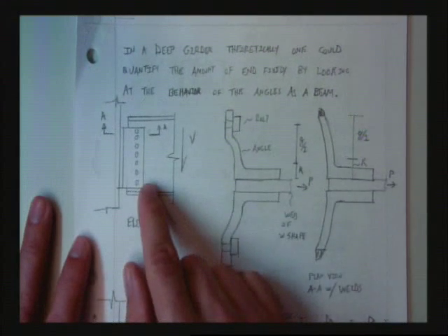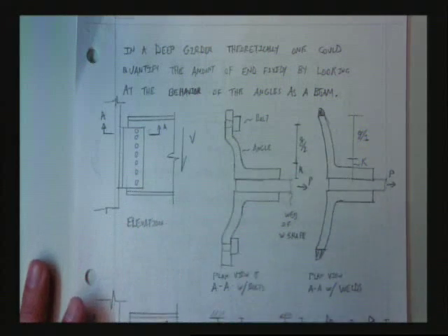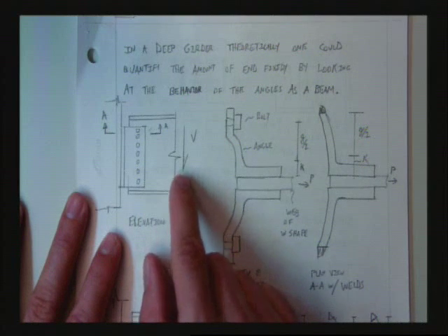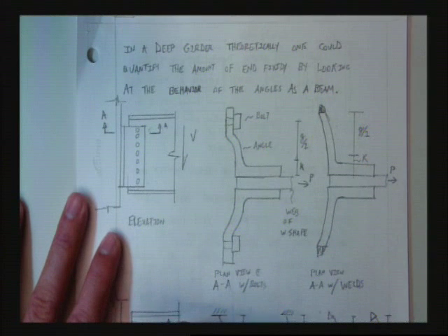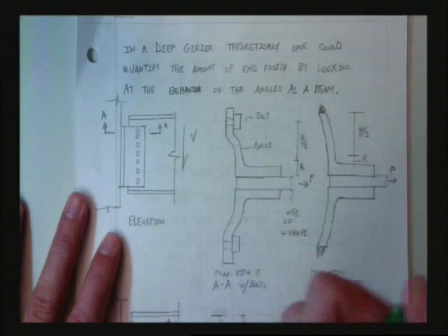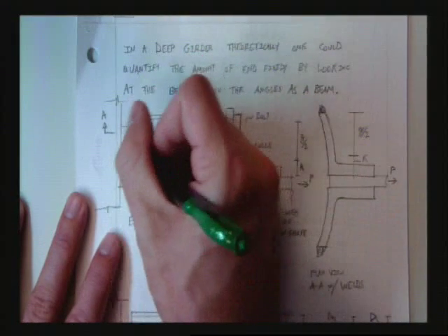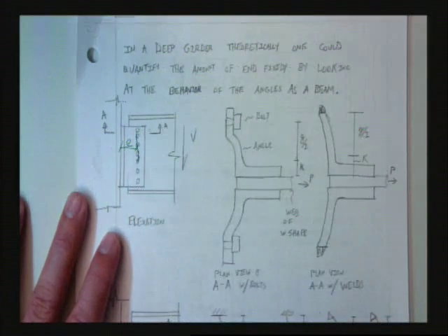So now what we have to think about is, okay, my gut tells me it's simple. I'm still thinking it's probably simple, but now since we have a shear on it, I'm going to imagine that it could be a moment connection, a partially restrained connection. I'm going to imagine that it could resist moment, and that when this shear comes through here, the shear is going to go through all the bolts, and that now this is going to be my moment arm. Does that make sense to everybody?